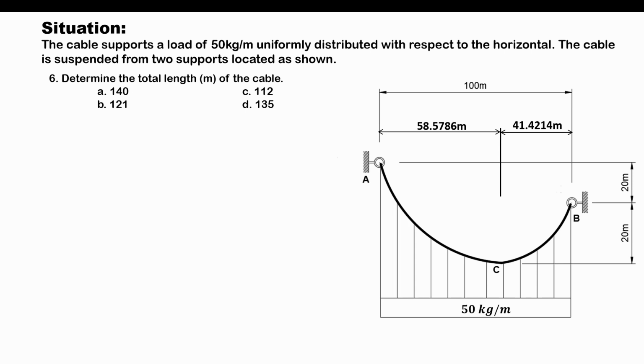In here, I will not be using that derived formula, but I will be computing the total length of the cable based mainly on the geometric configuration of the cable. However, my solution here is somewhat similar to that derived formula. We'll analyze a parabola, and depending on the equation of that parabola, we will compute its total length. So our solution here would also contain integral application.